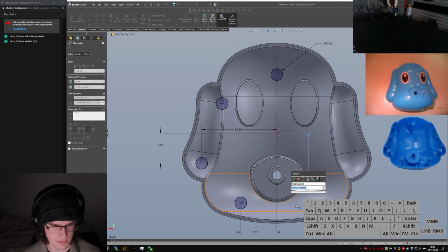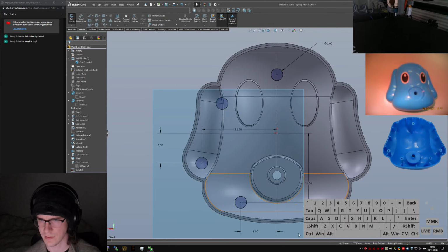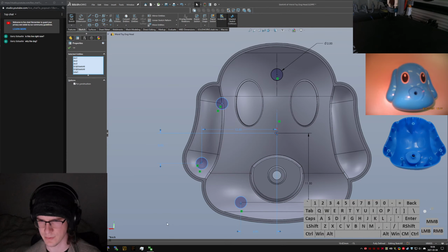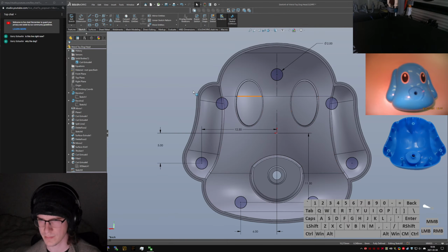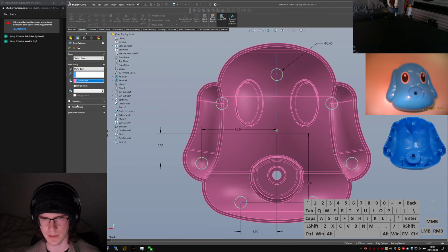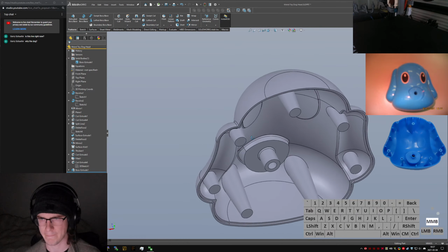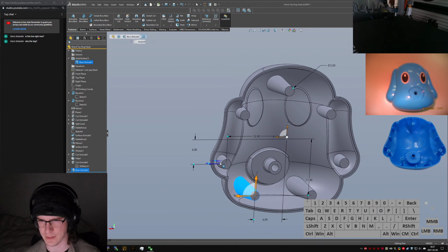And that's also there, seems fine. So now I can select all 3 of those and this midpoint line, do a quick mirror operation, and it just brings it right over. So we'll call those up to body, up to this guy, and then we'll draft outward by like 5 degrees. That's too much. Let's do like 3.